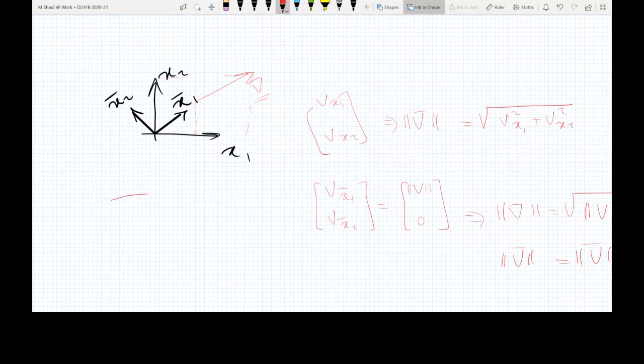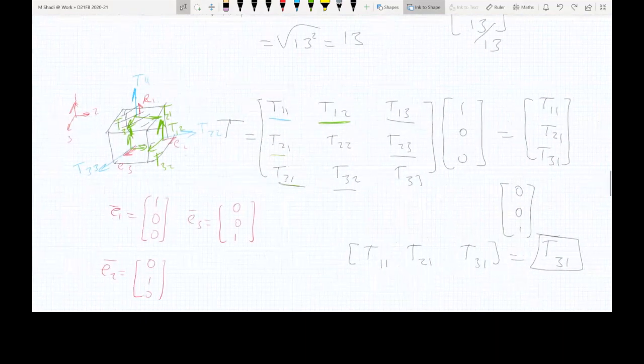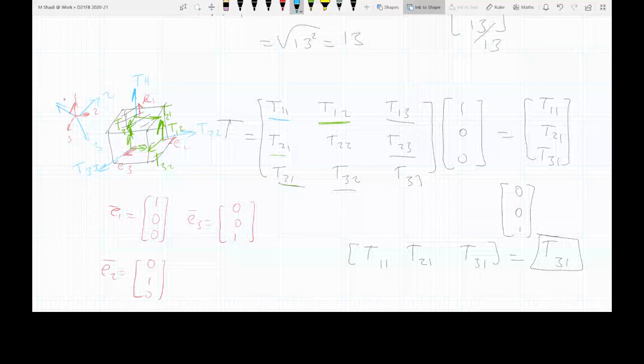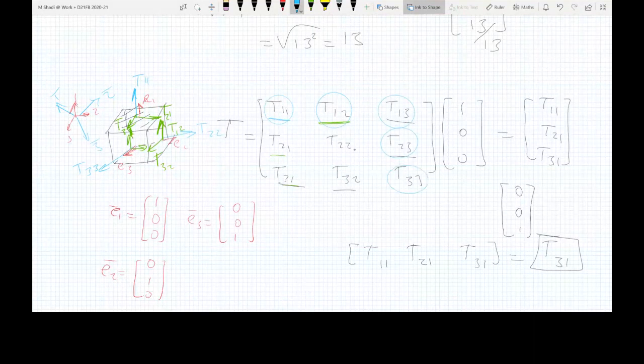Now I'm going to move back to the stress tensor, this stress tensor here. For a coordinate system x1, x2, and x3, this is projected into the full length or the full matrix here. Now, if you rotate the coordinate system, let us assume this is a new coordinate system. It is 3, 2, and 1, and this is in bars. These values here are all going to be changed. So these numbers will be different.